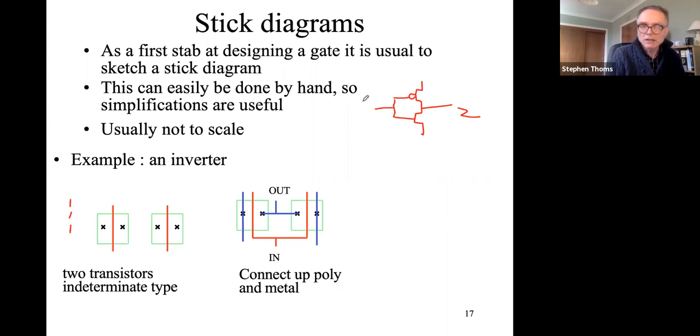So that's the input. So you can see that here, we've got the inputs are the gates connected to each other. The output, again, I've done the same message in the NOR gate. I've made sure the outputs are close to each other. Just make life easy. And then here, of course, we will have VSS and VDD.